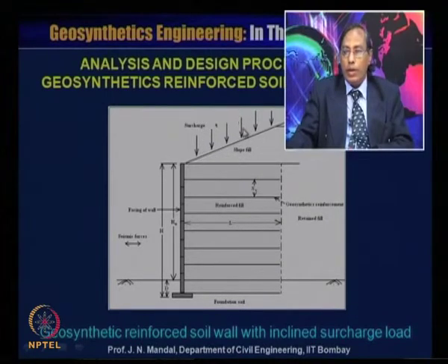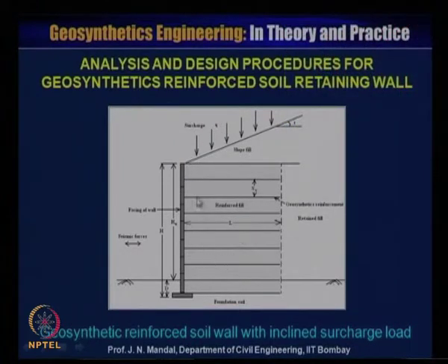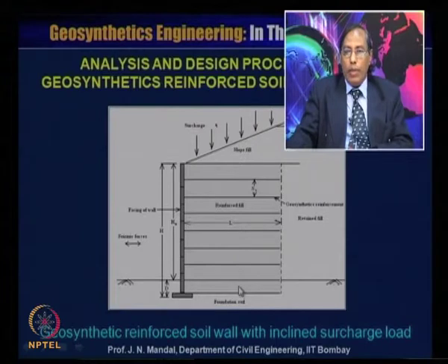Here you can see Q is the surcharge load, which is acting at an angle of beta, and this is the slope fill. And as I say, this is the reinforced fill. You always remember this is the reinforced fill, and this is the length of the reinforcement, L, and this is the foundation soil, and this is the geosynthetic reinforced retained fill, and this is the facing of the wall, and this is the depth of the embedment. We will design this mechanically stabilized reinforced soil wall, and there is a possibility of seismic forces, that also we will take into account.